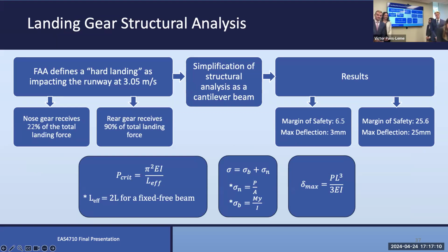So for this one, my feeling is that your design criteria is the deflection, 3 millimeter and some 2.5 millimeter. So for the rear gear, it was deflection, because obviously that's the most important metric in terms of protecting our camera. But for the front gear, deflection was not in the design criteria at all.